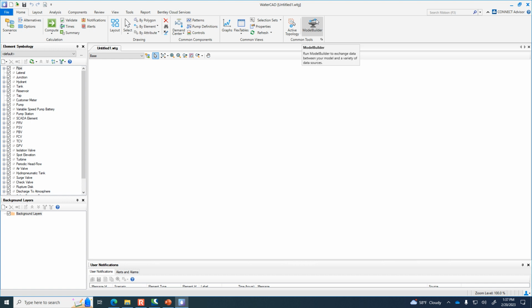So we're going to draw a schematic representation of our pipe network. It won't be to scale where I'm drawing. And that's one difference between this basic example I'm showing you today and your project. In the project I've given you a scaled map that you can bring up in the background and you can draw on top of the scaled map so that each of the pipes are the correct length. Here in this basic example, we're just going to draw a schematic representation of the network, and then we'll go in and manually correct the pipe lengths a little bit later.